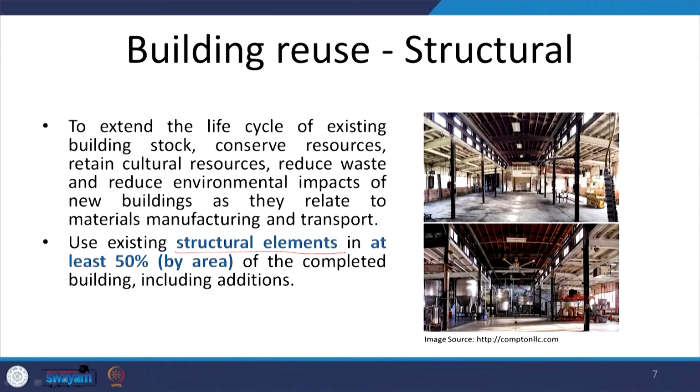If they need strengthening, that will be added, but all the structural elements or whatever portion of the structural element can be retained will be considered towards the compliance. And the compliance criteria is to use the existing structural elements in at least 50%, that is by area, of the completed building including additions.